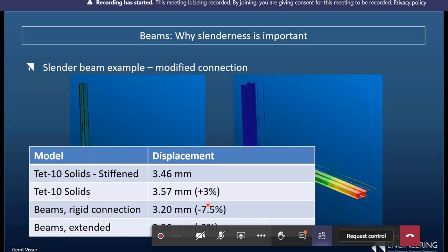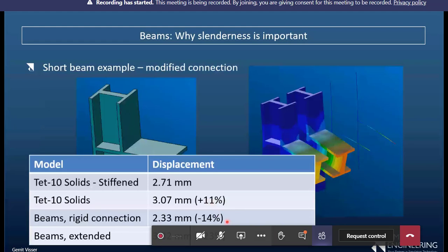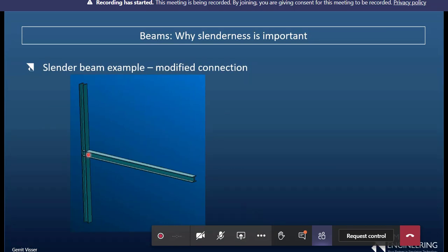So if I compare this, and I go back to this slide, just by increasing the length, doesn't matter which one of my models I have, I'm significantly more accurate by simply increasing the length of the beam. So why would that be? Simply because the effect of that local rotation becomes less and less the longer this beam becomes, because as it bends, if you look at far below, there it moves just a little bit below, but there it's a lot lower.